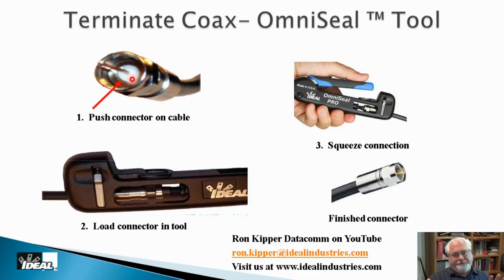Now, it's very important that you push the connector on the cable until that white dielectric is even with that little hole in the bottom of the nut you see here. It's the number one thing I see people not doing when they're putting on connectors. They're not pushing the connectors on all the way. And hence, when they compress it, it comes off pretty easily.